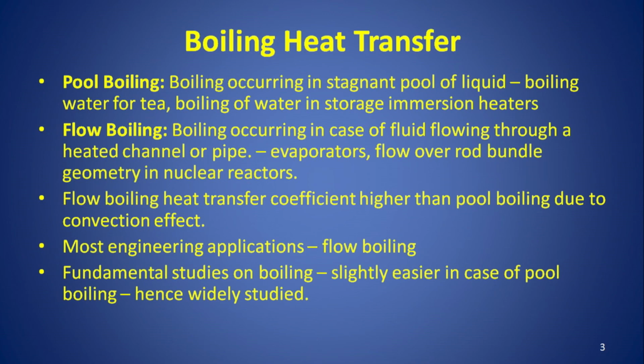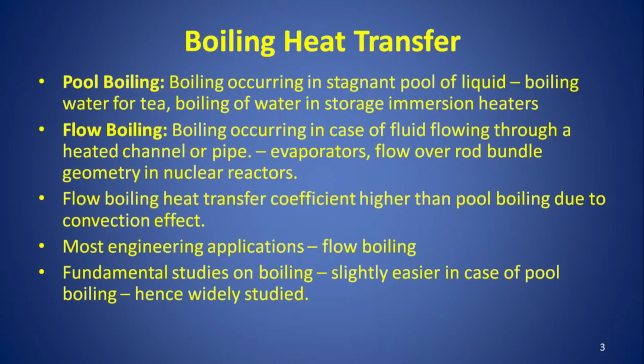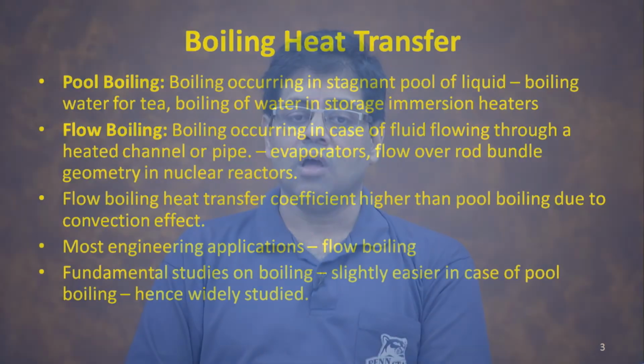Flow boiling heat transfer coefficient is slightly higher than for pool boiling because of the flow. Remember, in natural convection versus forced convection, the heat transfer coefficient in forced convection was much more, and that much more aspect came because of the bulk flow velocity involving a non-dimensional number called the Reynolds number. Same thing here, pool versus flow boiling, we would have a higher heat transfer coefficient for flow boiling as opposed to pool boiling. Most engineering applications, as I said, involve flow boiling, and we are going to talk a little about pool boiling,